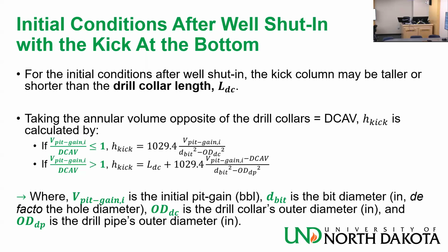Yeah, you have a range, but you're never 100% sure, just like you are not 100% sure what the FPP is. You know what the mud is because you read it from the surface. You know what the SIDPP is. You know what the SICP is because you ask somebody to record them for you. They are reading them from the surface, and you know the pit gain, but you don't know anything else for certain. And hopefully you know what the BHA looks like.